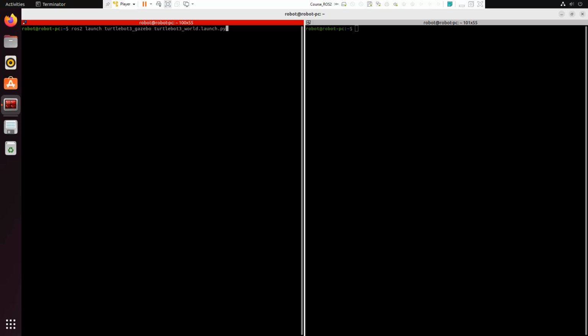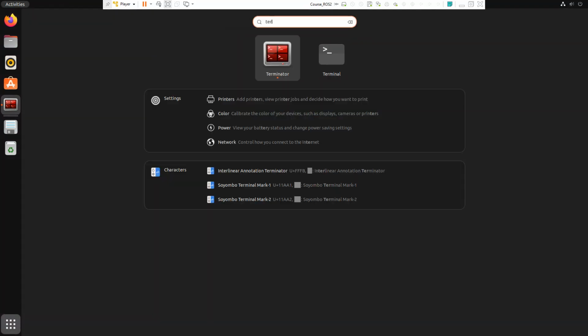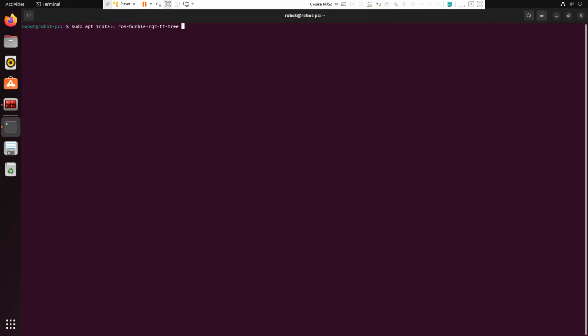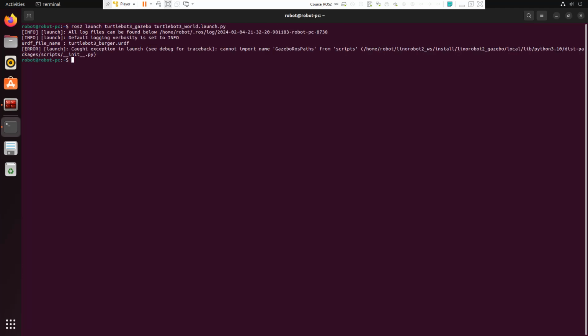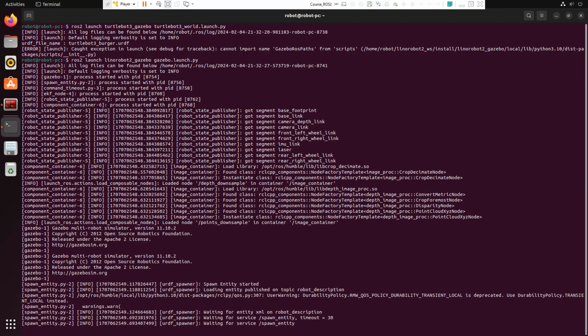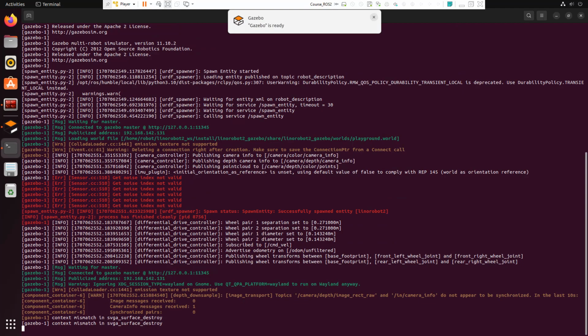Yes. There I saw that they are using this nav2 bringup. It is a package. So I just copied that launch file from where that nav2 bringup was, and then edited that launch file according to my directory. Where they were using that rviz config, I replaced it with my rviz config, and that map file location I replaced with my map file. Then it began to work, and I was able to load the map and perform the operation.